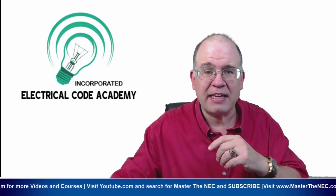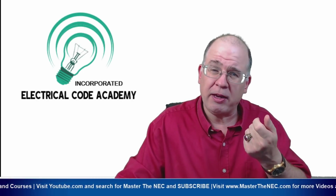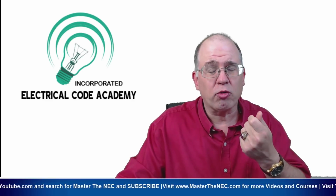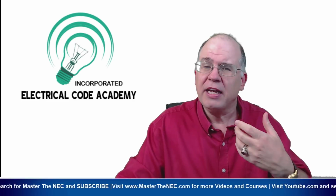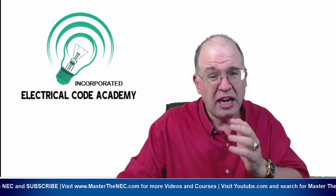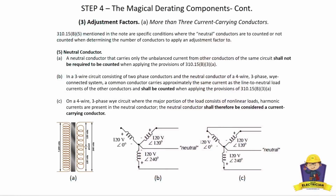So you have to take that into consideration. That's another example of why you might see some neutrals inside of a panel of a 3-phase system with high harmonics, where the neutrals that were white end up turning gray or grayer or brown or whatnot. It's because the current traveling on that grounded neutral conductor is exceeding its rating, and you might need to check that. It's starting to damage the insulation, so keep that in mind.